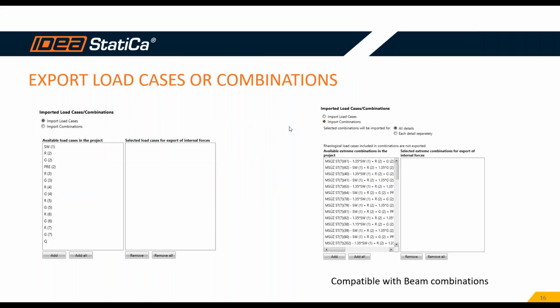From the point of view of the export of the load cases or the load combinations, you have the choice. You can export the load cases and create the combinations inside the Detail application, or you can export all the created combinations which were done by the combinator used in IDEA StatiCa Beam. I think there is a higher benefit in this, as it is compatible with the beam combinations, and after rearranging or redesign, it's